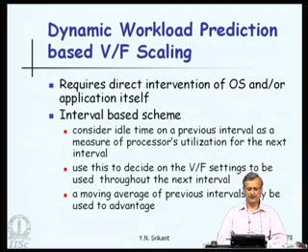This requires direct intervention of the operating system and or the application itself. Interval based techniques consider, as I said, the idle time in a previous interval as a measure of the processor's utilization for the next interval. So, the assumption is whatever happened in this interval will happen in the next interval also. Use this to decide on the voltage frequency settings to be used throughout the next interval. It is also possible to use a moving average of the previous intervals, and this can possibly give some better advantage.